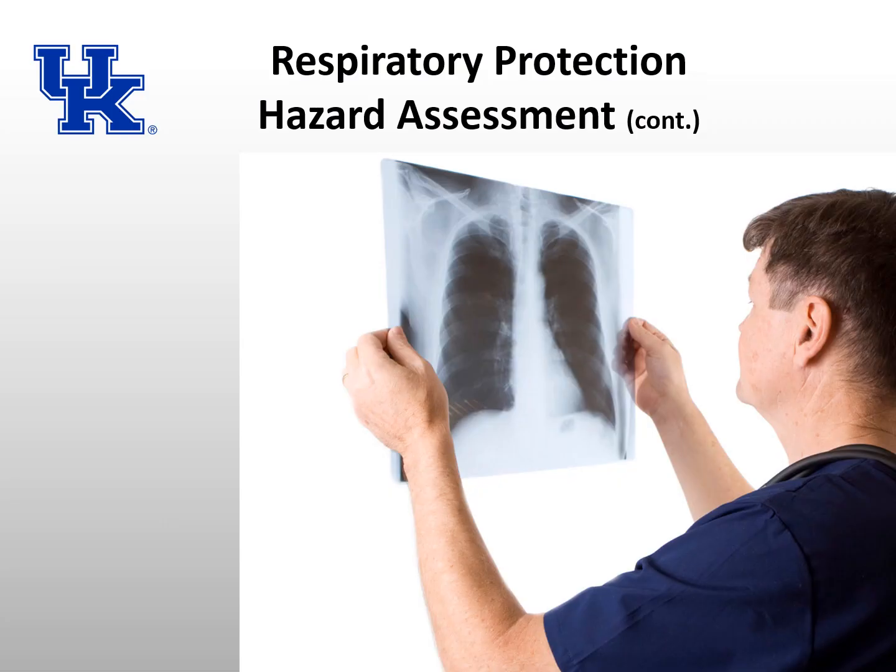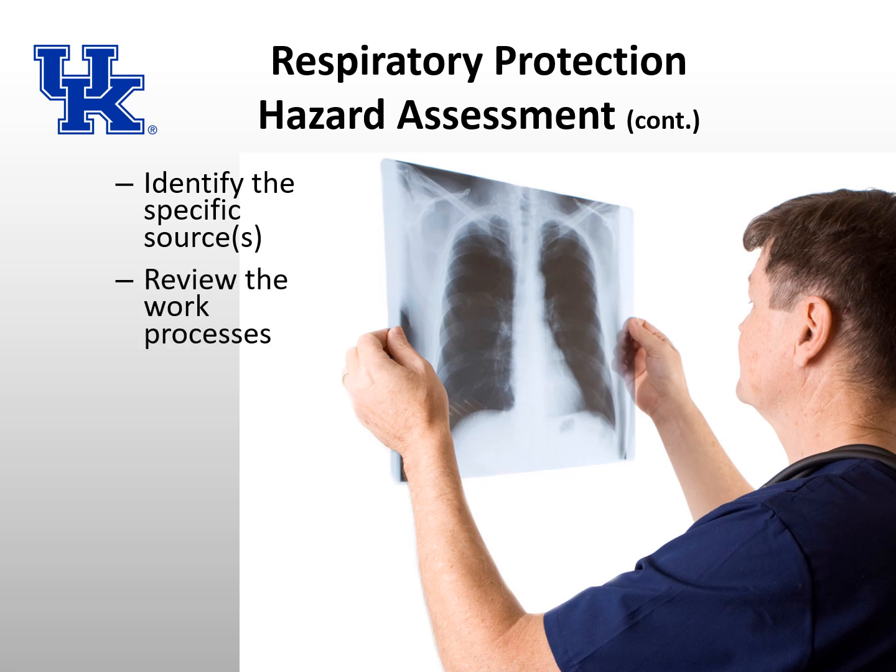After the assessment has identified the potential respiratory hazards, your employer takes the following steps. First, they identify the specific sources of respiratory hazard. Then they review the work processes to determine where the exposure exists and the magnitude of the exposure. And finally, if necessary, they monitor the exposure to measure the degree of the hazard.